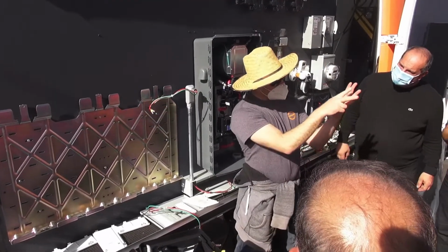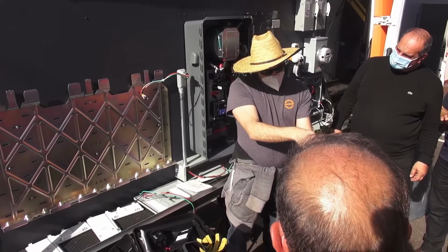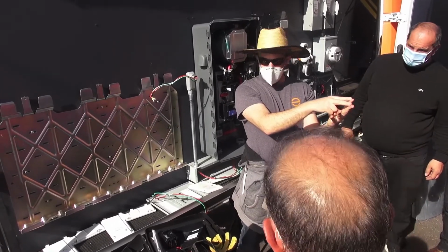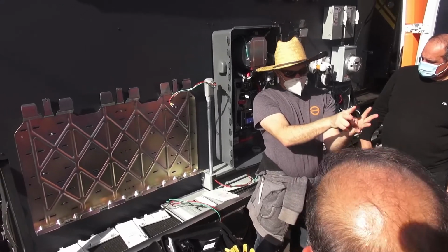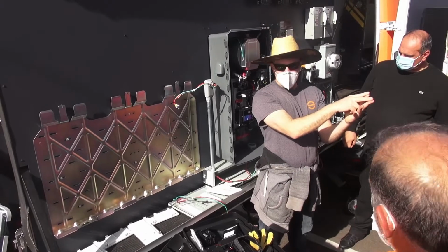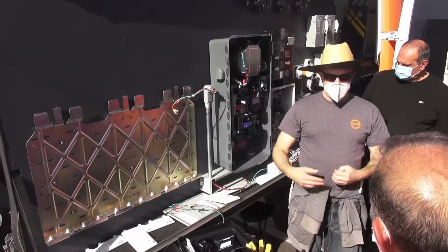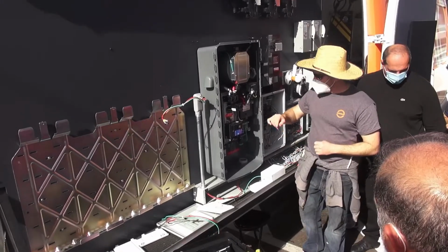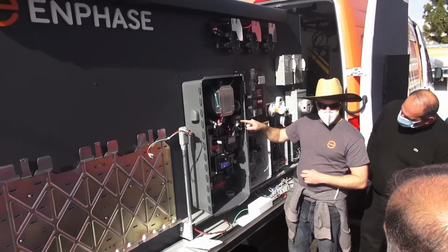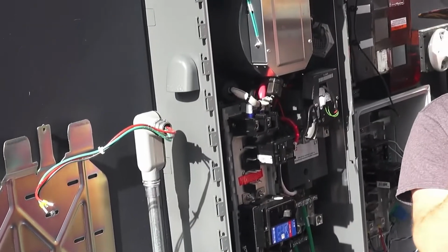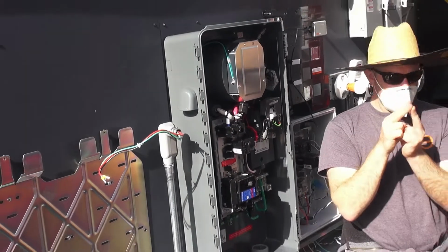A transfer switch goes from utility typically to a big, ugly, smelly generator, right? When we think of a transfer switch, the house goes dark, and then the generator warms up, and then the house gets power again, right? We actually use an item that's similar to that, but it's simpler. It's called this MID switch, Microgrid Interconnect Device. It doesn't go A to B, it just goes open or closed, right?